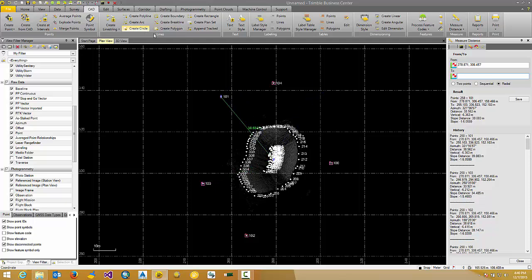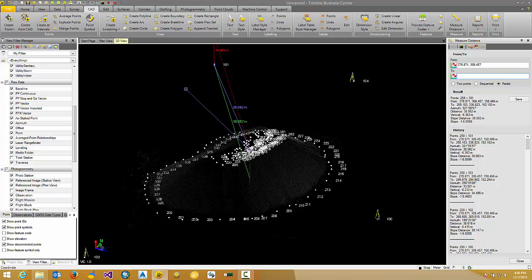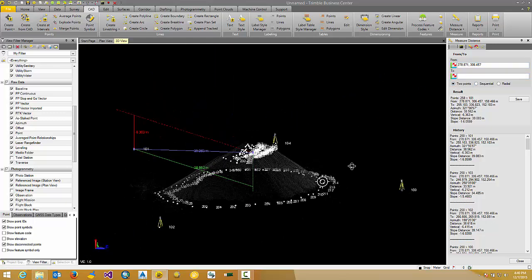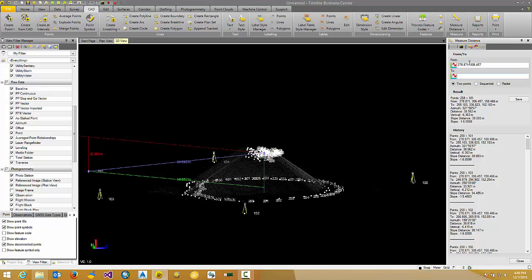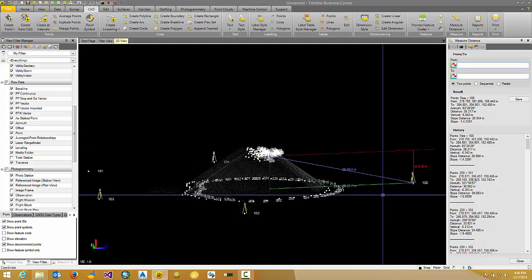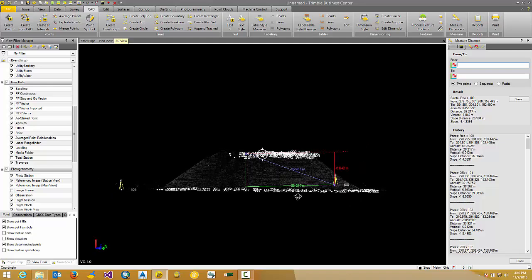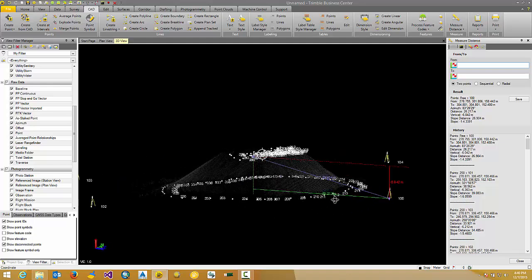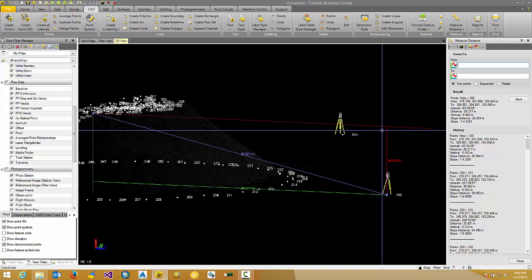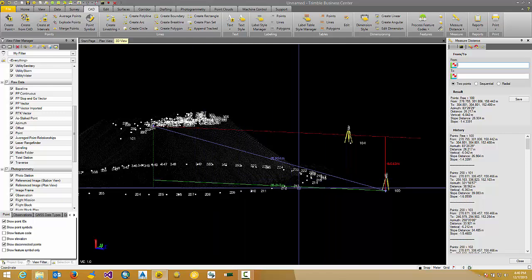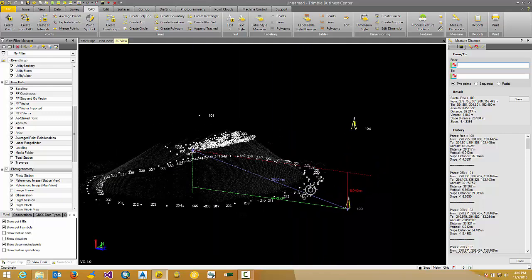The new cool option to save is especially valuable if you're working in 3D. So if you're measuring distance between 2 points in 3D view, so let's say you want to get distance from the top of this stockpile to this point, station 100. Notice that in 3D view now you can see the slope distance, the vertical and the horizontal clearance between any two selected points. In addition to that, you can now choose to save that information.